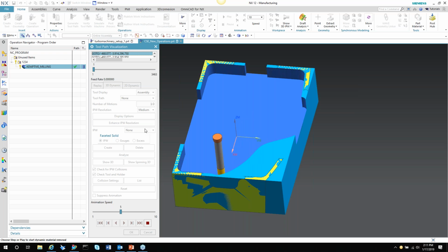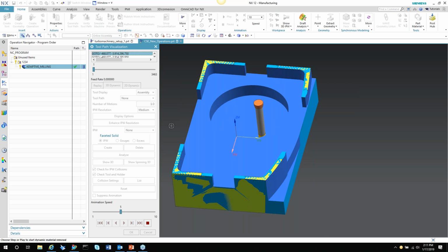And as I said, if you're a job shop or even producing your own components, if you're not working with an advanced roughing strategy like this, you're very easily going to be bid out, because you're not going to be able to compare to the traditional half diameter, 75% cut patterns that traditional roughing algorithms give you. So you can see the benefits of this style of roughing pattern.